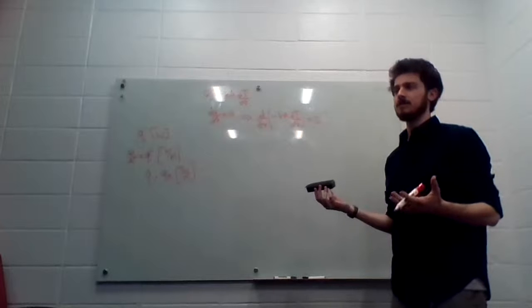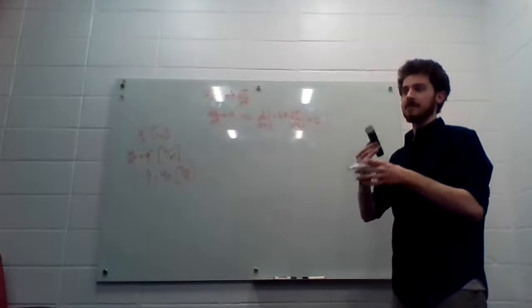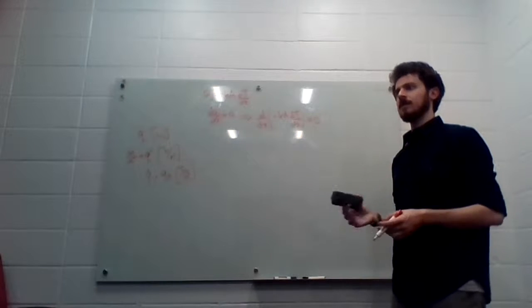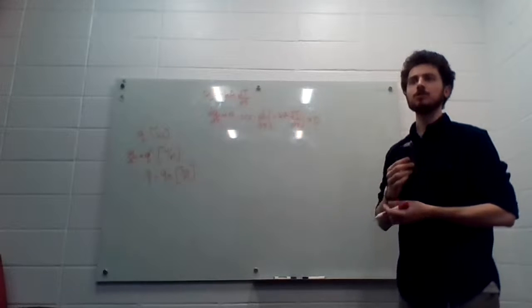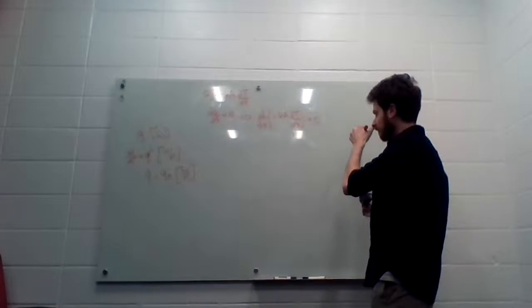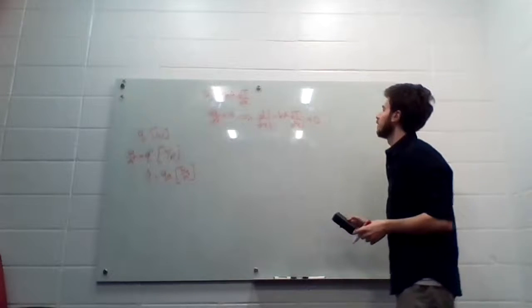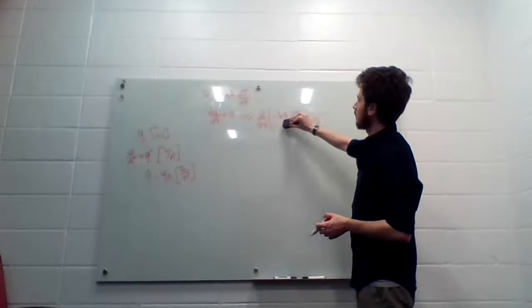And the cool thing about the heat diffusion equation is Q is no longer in it. So we would have a complete description of temperature with relationship to x, and you don't need to solve for Q to use that equation. That's what we're working towards. And so we just eliminated Q, and now we've got something just in terms of x, T, k, and A.